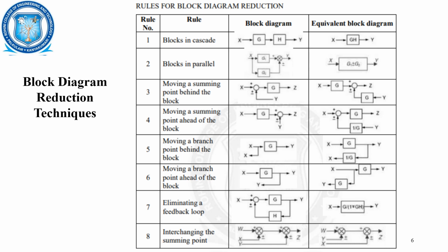If two transfer functions are connected in series, they can be multiplied, that is, they can be cascaded. If two transfer functions are connected in parallel and in a forward manner, here it is from left to right, and here it is also from left to right, then for that forward representation of summation or subtraction, we can reduce them into one as either addition or subtraction.